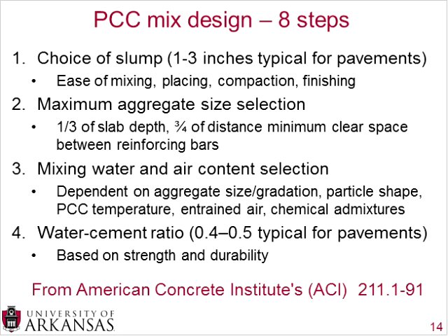So when we're talking about Portland cement concrete or PCC, you can also add something called chemical admixtures. And those admixtures can do all sorts of things. Pretty much if you have a set of concrete and you want it to do something different, chances are there's a chemical admixture out there that you can add to the PCC, which will enable you to do something different, something extra, something more advanced with that mixture.